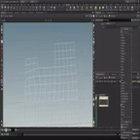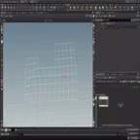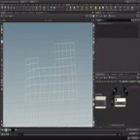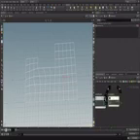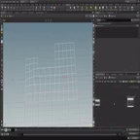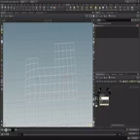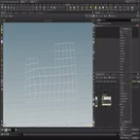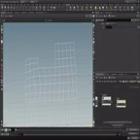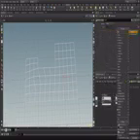And to do this, I will multiply it because there are some inaccuracies within Houdini, as always. Well, because this is very sensitive to very slight changes. So I'm going to round it down to a few decimals. And to do that, I'm going to place down a multiply. And then I'm going to be placing down a round to integer. And then a divide node.